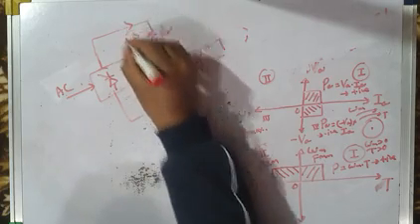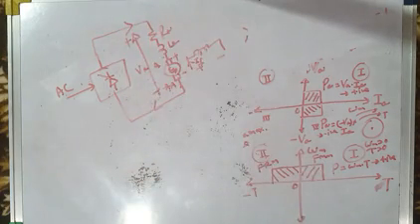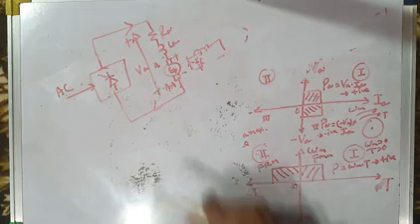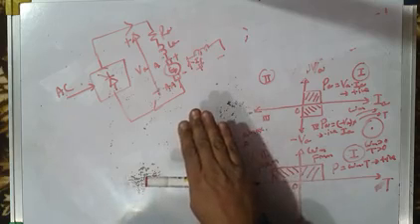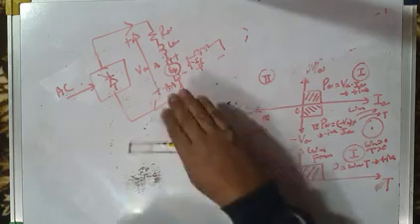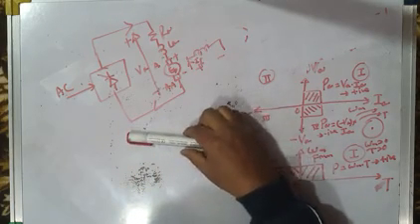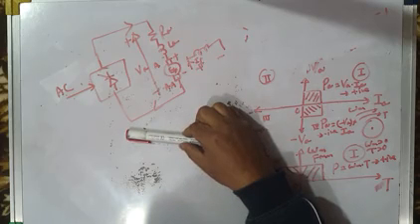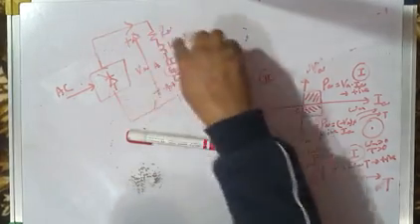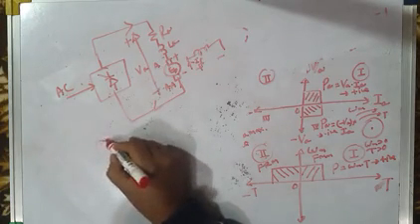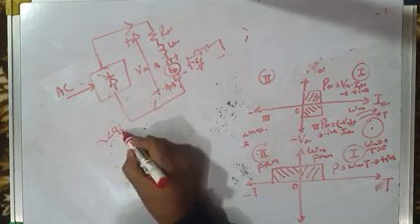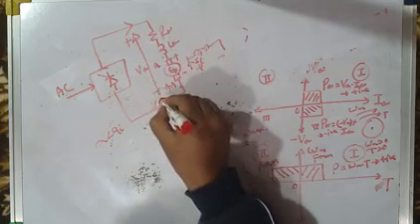In the motoring mode, current is flowing like this. Okay. Now let us suppose our drive is not a train, it is not a vehicle, or it is not any other load. It is a hoist. Say for example, what does a hoist do? In the motoring mode, hoist develops a torque. Say your machine is operating in the motoring mode. Alpha is less than 90 degrees, I mean 0 to 90 degrees is alpha. Average output voltage is positive.